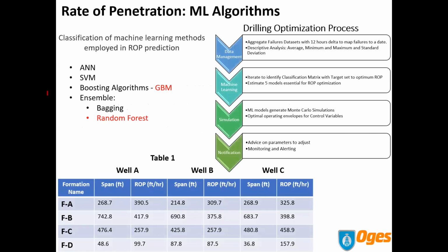So the data in real time is collected from, obviously, drilling data acquisition units on the surface of the rig. So we can collect, for example, as I mentioned, weight on bit, RPM, torque, standpipe pressure, the flow of the pumps, the depth of cut. These data are depth index sampled, usually at about 0.5 feet interval. And so in this case study, we're looking at 3 wells used in this study to span a total footage of some, I believe, 1,800 feet.